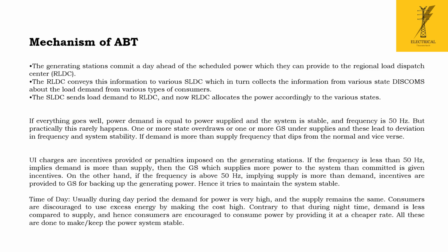Similarly, on the other hand, if my supply is more than the demand, I am sending 5 megawatt, but the demand is only 2 megawatt, then the frequency will be very high. Okay. Yes. If demand is more, the frequency will be less.